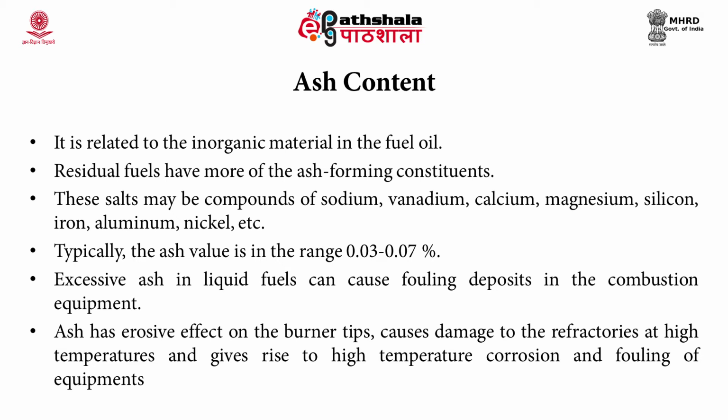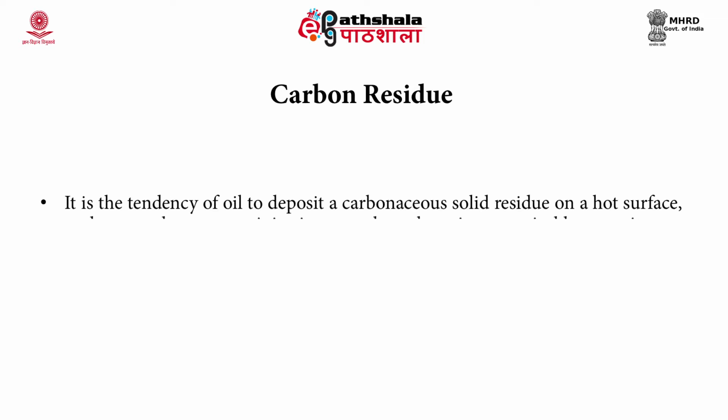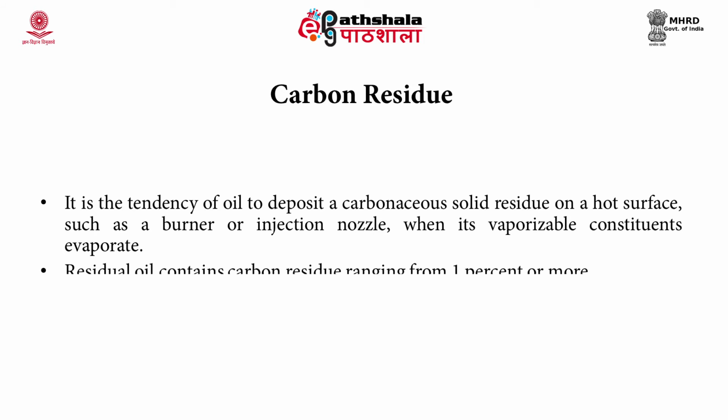The organic residue present in the fuel oil is known as the carbon residue. The tendency of oil to deposit a carbonaceous solid residue on a hot surface is common. It is mainly on the burner or injection nozzle, when its vaporizable constituents are evaporated. So, carbon residues are deposited on these parts. Residual oil contains carbon residues ranging from 1% or more.